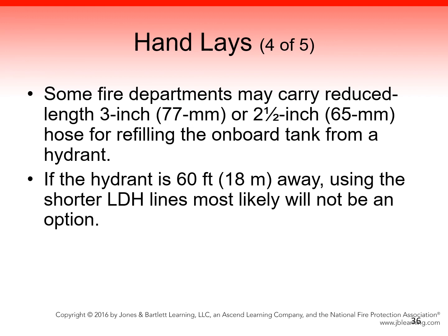Keep in mind the direction in which you need to go. Your goal is to minimize sharp turns and twists in the hose, thereby reducing kinks and severe bends that might reduce the flow. Watch out for any oncoming traffic while operating in the roadway. Always wear your traffic safety vest as required by your department.